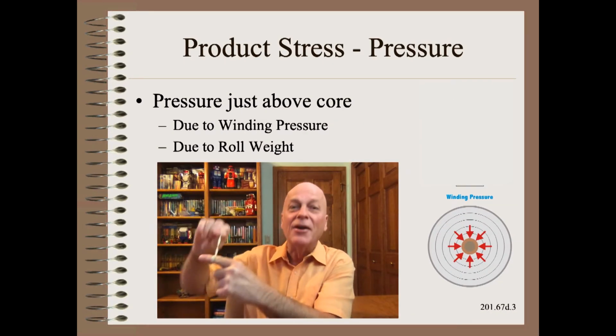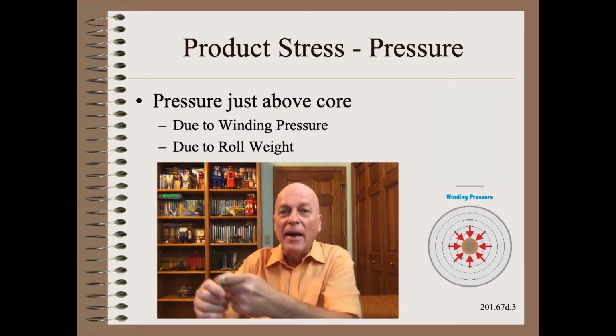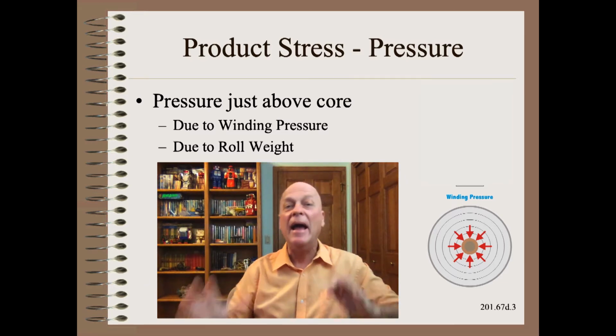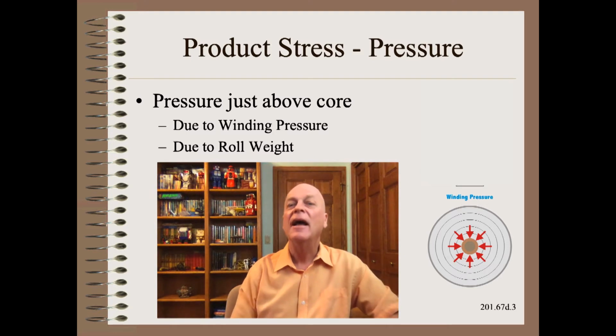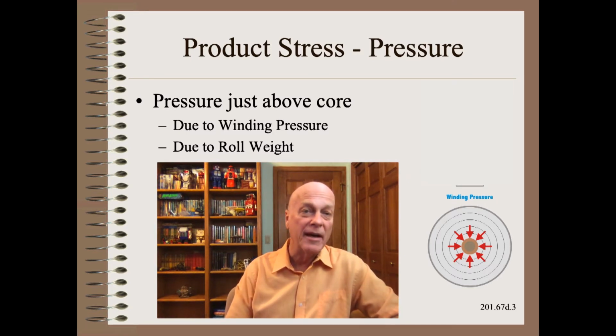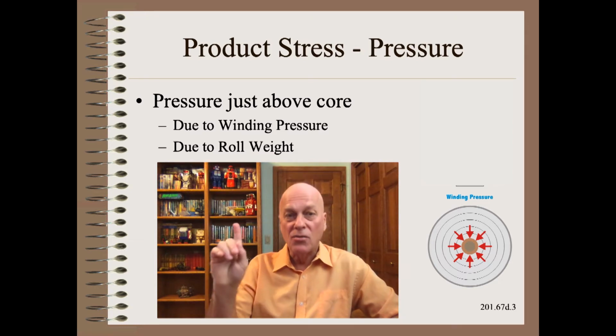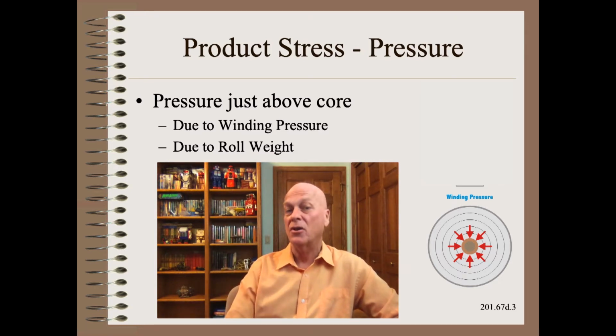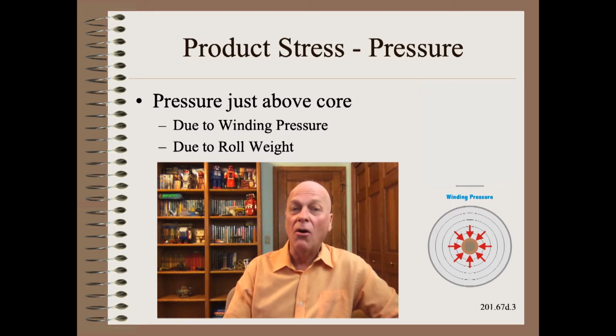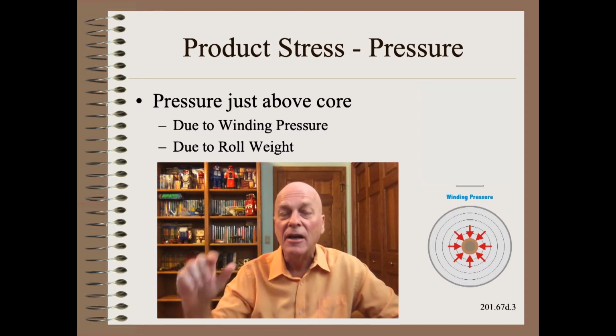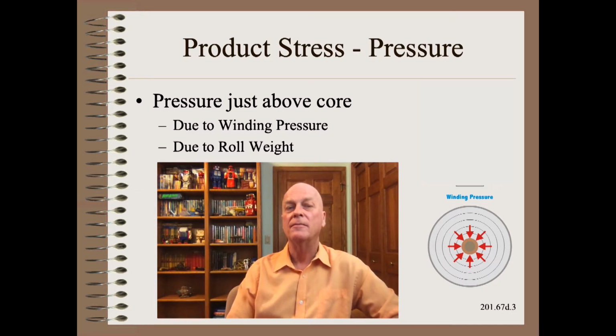Each layer of the web that you add to the winding roll adds to the pressure. As we learned in our Web 101 training, that pressure peaks near the core. That is one reason that you can crush the core. However, not only can you crush the core, your web product can also crush if it is not durable.